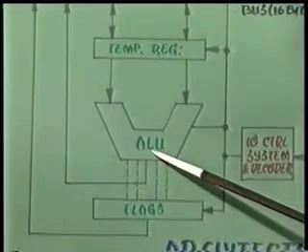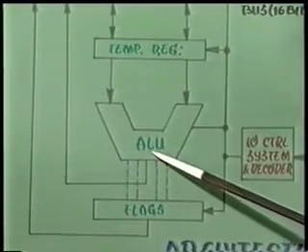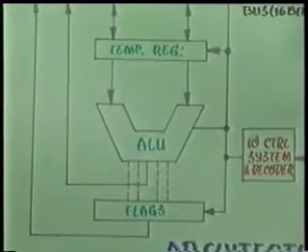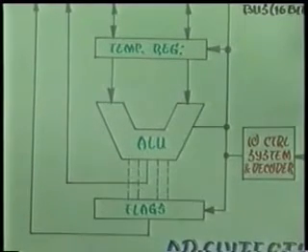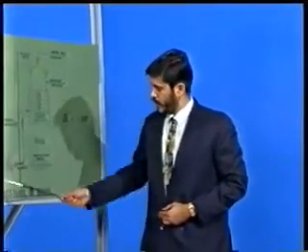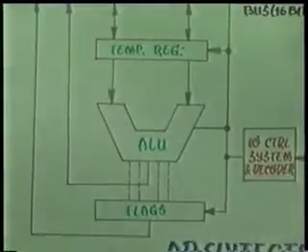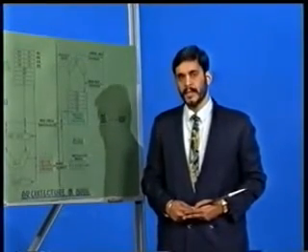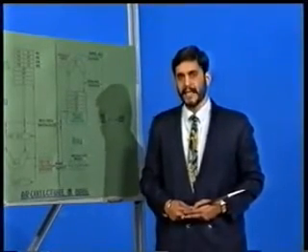The 16-bit arithmetic and logic unit, ALU, has the same role which it had in 8085, that is, of carrying out the various arithmetic and logic operations. The flag register in 8086 consists of 9 flags. These flags are further subdivided into two groups, 6 conditional flags and 3 control flags. The flag register is shown in the graphics.